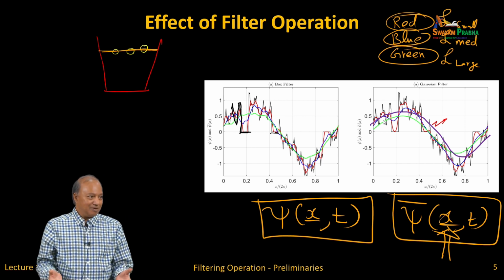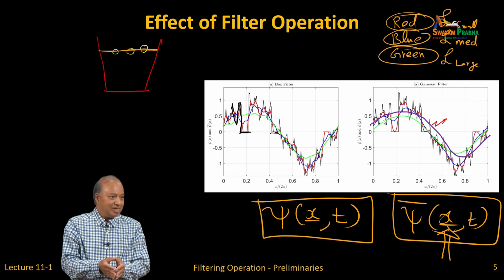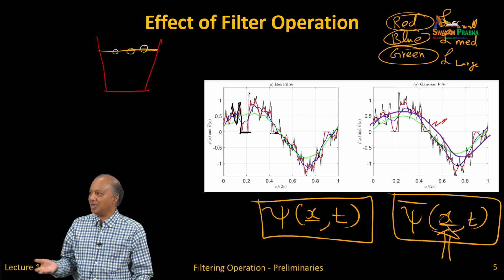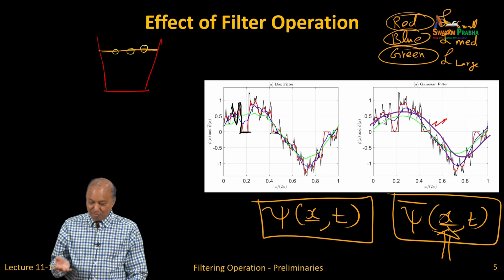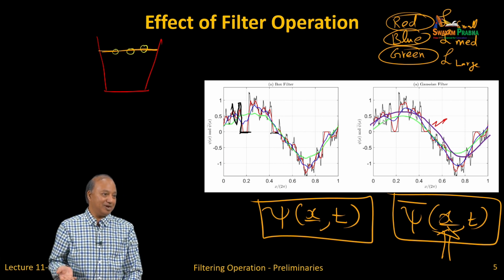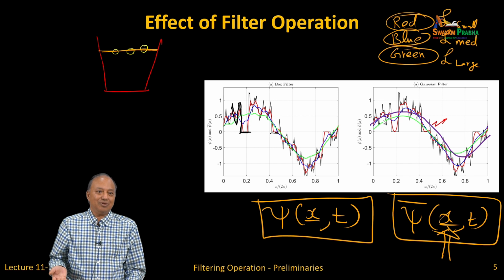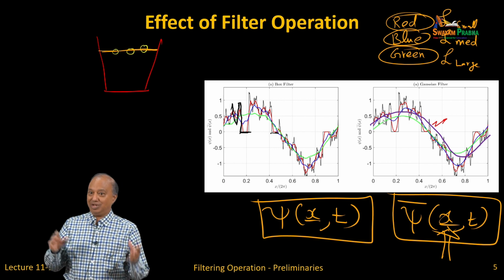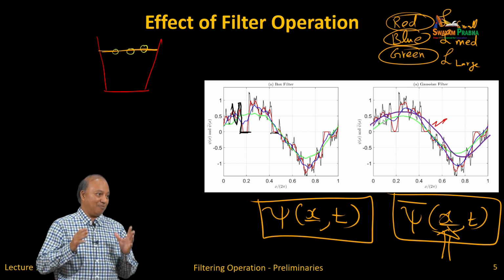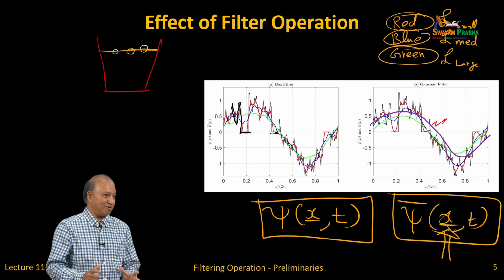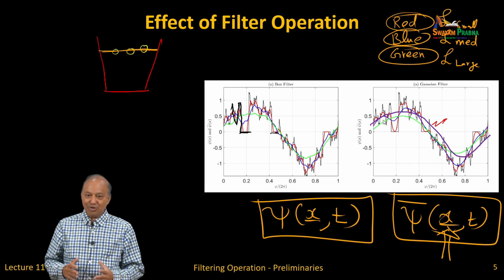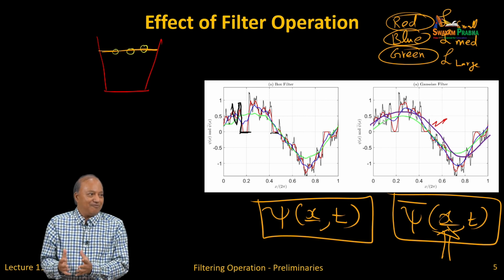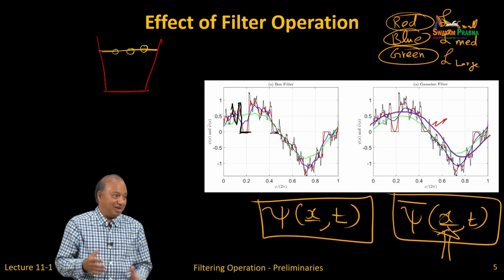therefore what happens is when you do that, when you put a fine grid, you are solving a different problem. You are solving for the green line or the blue line or the red line depending upon your grid. Therefore, how can you expect your answer to be the same? But in RANS, it is only the purple line, and you can say I am going to put more and more grid and I am going to get the purple line, much more sensible. In LES, you are shooting a moving target. Therefore, every time you resolve the grid finer, you want a better answer. So it will never be stable.